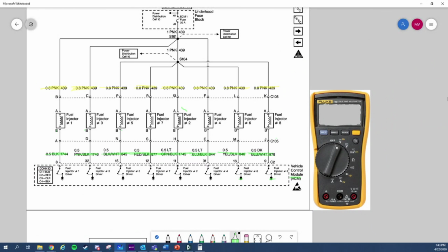Power. Well, we have a constant power, and it's grounded out to pulsate it, but what tells an injector to actually shoot the fuel? Isn't it fuel pressure? Not fuel pressure. How do you determine? Think about it. Your combustion engine has to have three things: air, fuel, and spark. Okay, so does this distributor have any type of sensor on it?